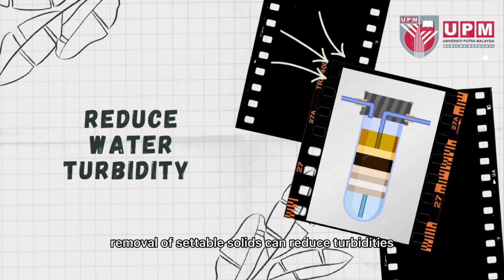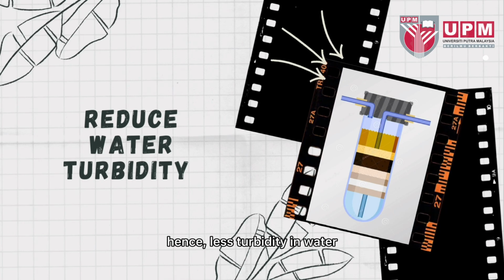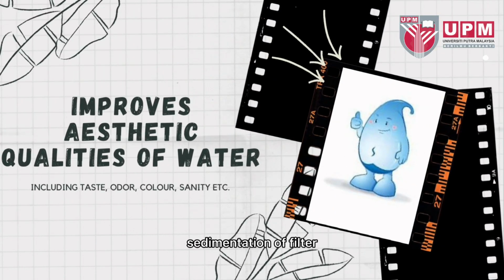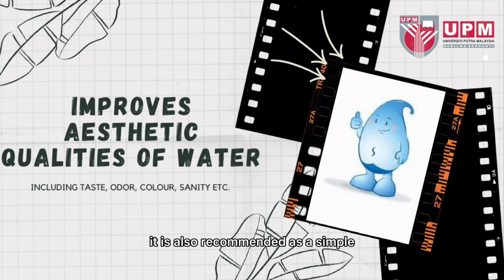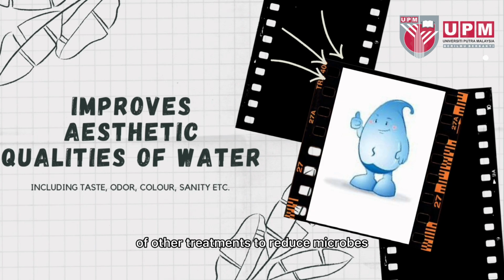Removal of settleable solids can reduce turbidities and make the water more amenable to other treatment methods to reduce microbes. Hence, less turbidity in water can improve penetration of UV radiation, decrease oxidant demand, and decrease solids-associated pathogens. And last but not least, sedimentation filtration improves the aesthetic qualities of the water and thereby increases its acceptance by consumers. It is also recommended as a simple pre-treatment of household water prior to application of other treatments to reduce microbes.